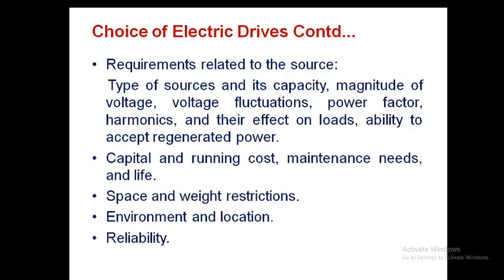Requirements related to the source: type of sources and its capacity, magnitude of voltage fluctuations, power factor, harmonics, and their effect on loads, and ability to accept the regenerated power.